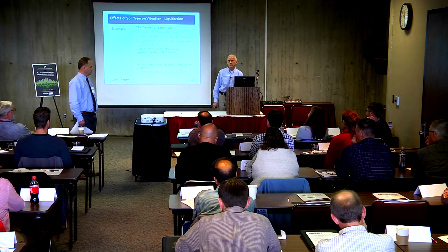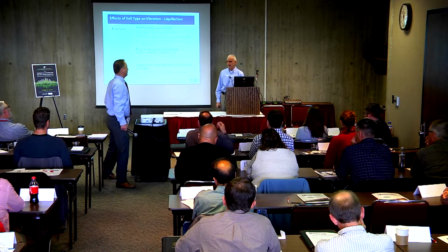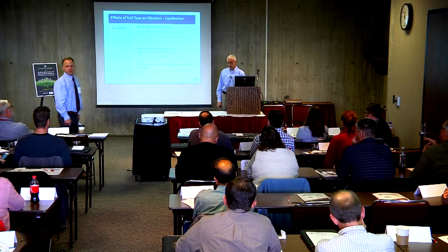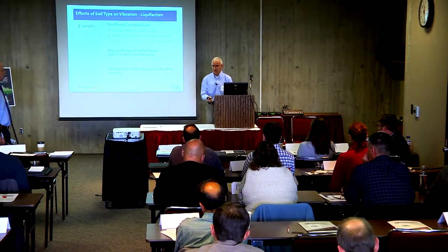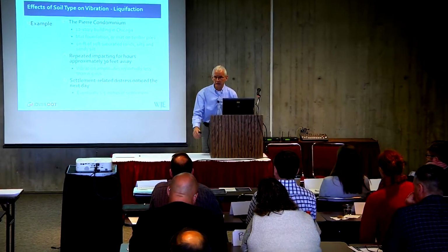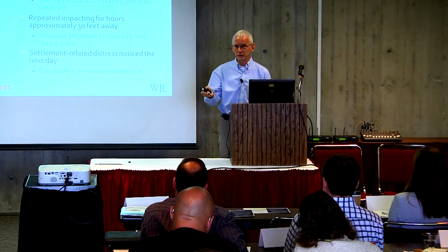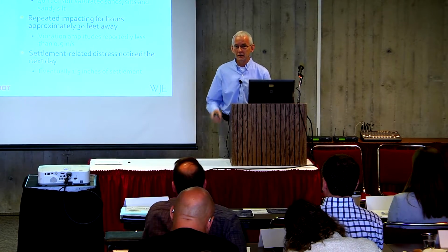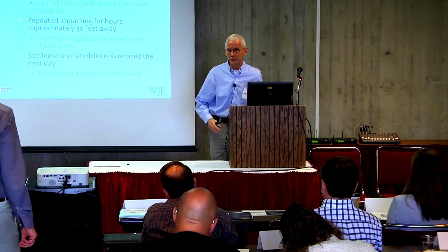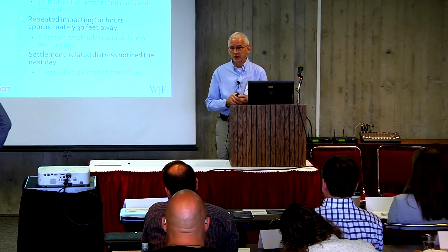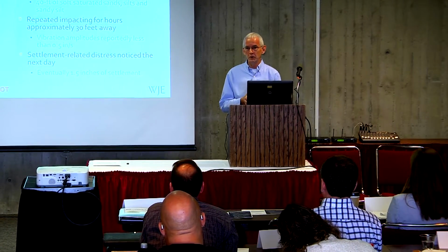Well, with caissons, usually you're augering down to get through, and that's a little bit different than vibratory pile driving. That's essentially what it's doing. It's dispersing the soil so the pile slips into the ground, and you can tune the driving frequency to a resonant frequency of the soil to get it in. You do run the risk of generating a resonant response that travels farther through the soil in the process. But if you're not too worried about damaging nearby structures, that should be okay.